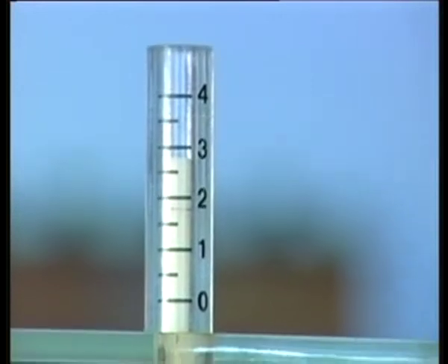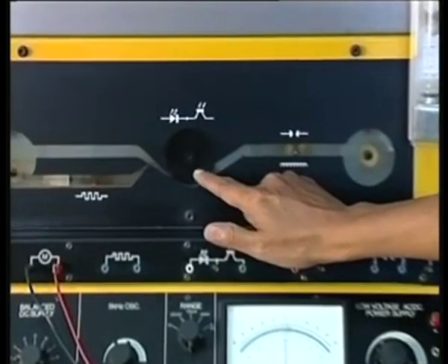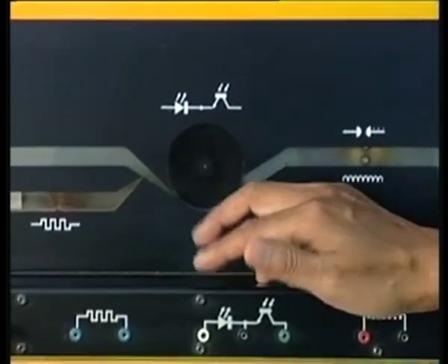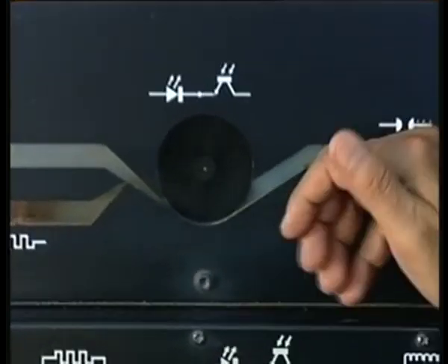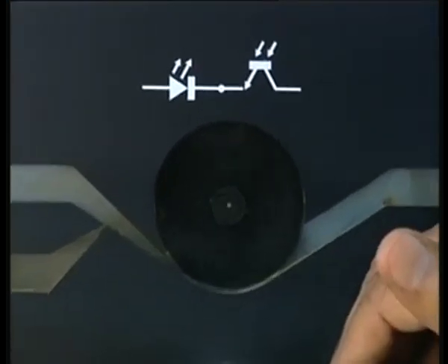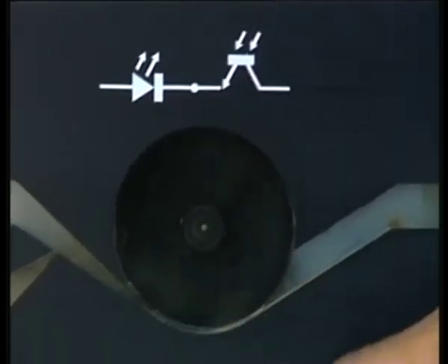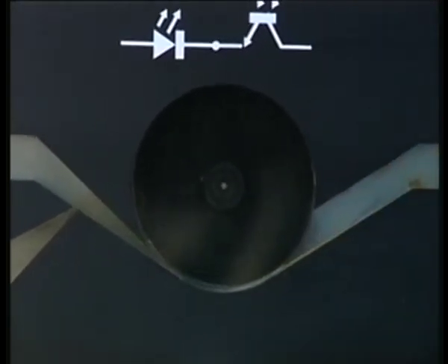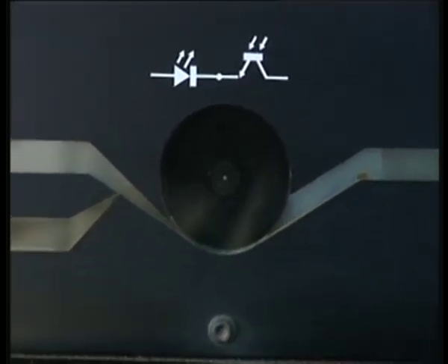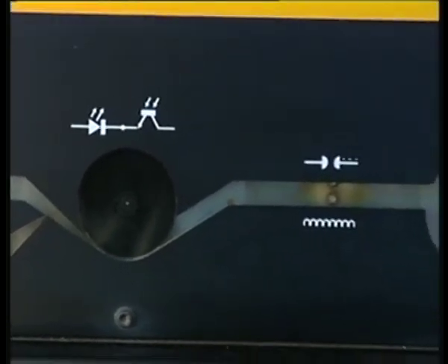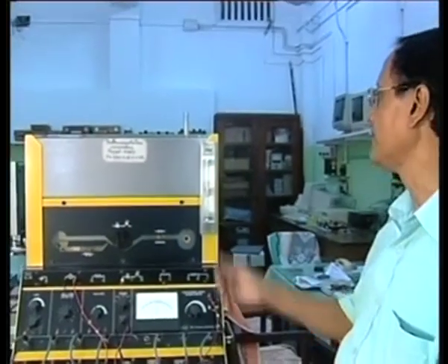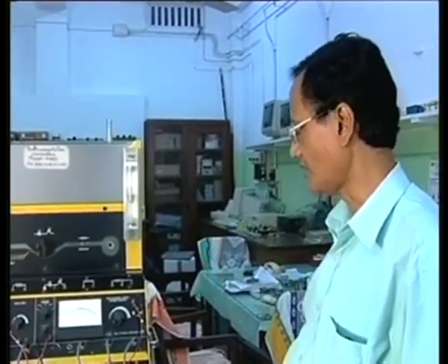And you can see here, interestingly, this is an electro-optic flow meter. If I go to the back side, you can see that there are 4 spots and there are lights falling on the flow meter, and for each complete rotation I am getting 4 pulses. So suppose I have 10 rotations, accordingly I can calculate how much the flow is moving. So it has a direct electrical output. Otherwise, you can see here this flow meter has no electrical output.